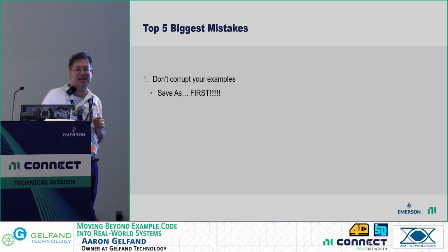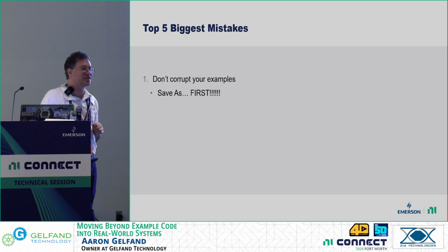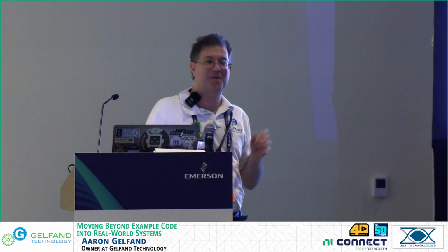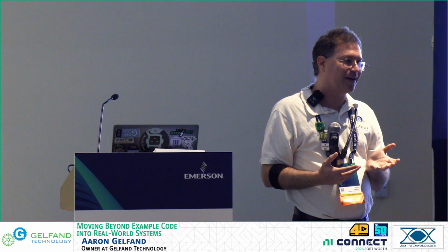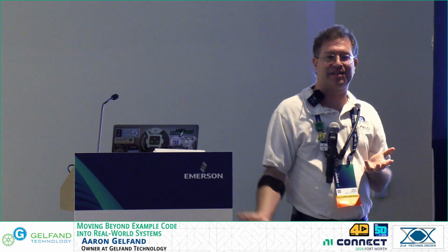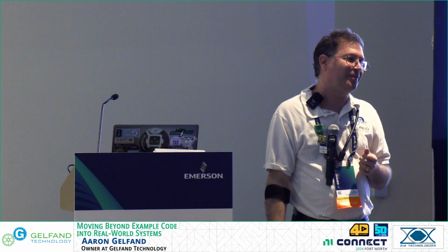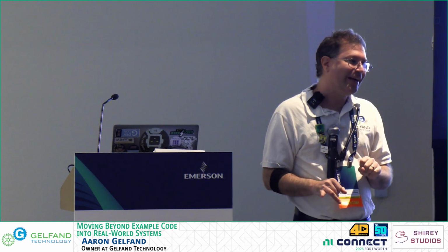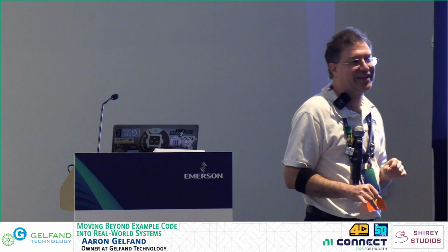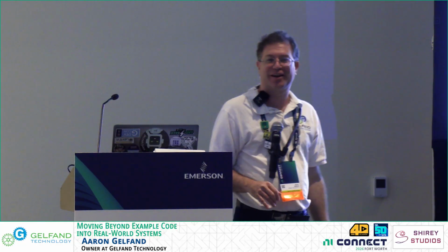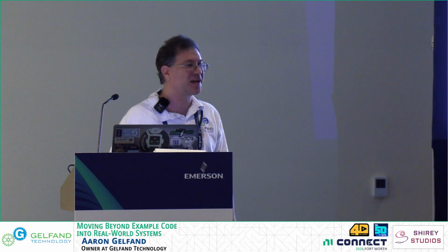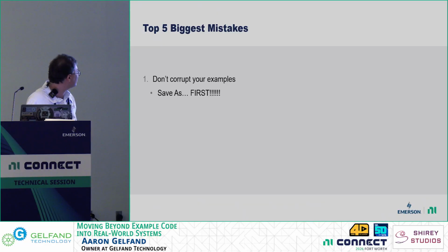Don't corrupt your examples. Use File, Save As first. A very frequent mistake is people go in and start modifying the example to do what they want. They make a mistake, they want to go back, but they've already saved and overwritten the NI example. And then it's like, oh boy, do I have to do a repair of LabVIEW now? And unfortunately, yes. That is something NI is aware of, and they've been trying to come up with a good idea on how to solve it for years, and we may finally see some ideas coming to fruition in the next year or 3.